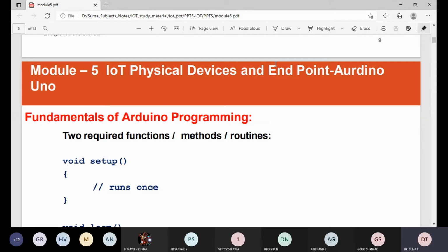Then select the serial port where your Arduino is connected, and it will show the right port and display information about the board.